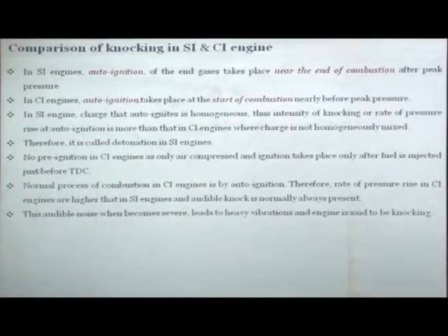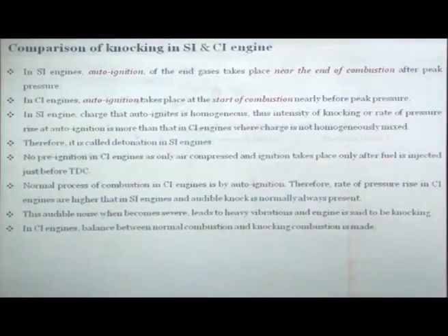The normal process of combustion in CI engines is by auto ignition, therefore the rate of pressure rise is higher in CI engines compared to SI engines, and audible knock is normally always present even in normal combustion conditions. When the audible noise becomes severe, it leads to heavy vibrations, and then the CI engine is said to be a knocking engine. So in CI engines, a balance between normal combustion and knocking combustion is made.